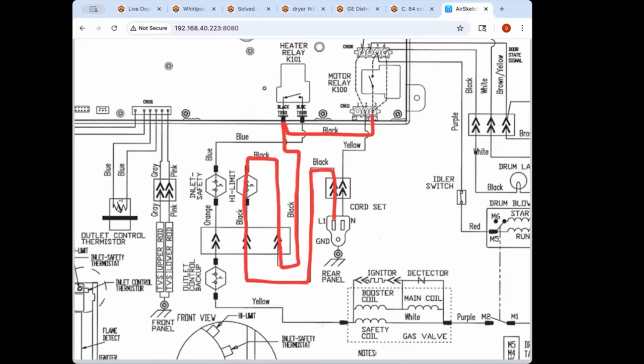Is that one of those white ones or is it a different style? I don't know about the style on this one. I actually had a blog post on this, something very similar under GE. It was an electric dryer, but it had this exact scenario where it runs the L1 through this thermostat, and the thermostat that I had was charred. So it's sometimes making a connection, sometimes not. I got some up close pictures of the actual charring of the thermostat.